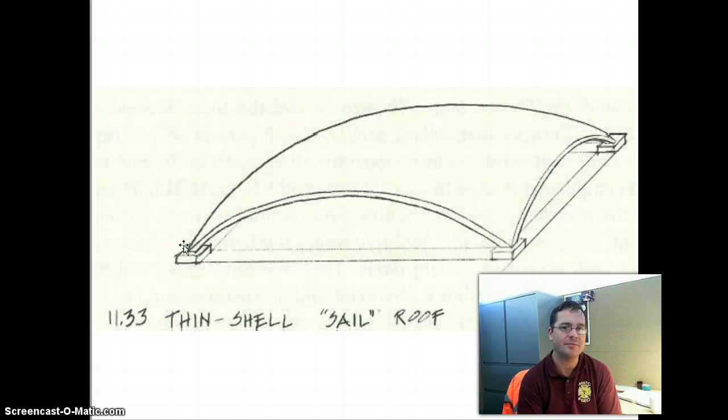You have to have something to keep the soil from sloughing into the excavated hole, because typically the walls of the excavation need to be near vertical. They don't have the luxury of cutting the walls of the excavation back beyond the friction angle of the soil. So there'd be a number of ways you could retain that. You could drive sheet piling, for instance. You could drive piles and drop in breastboards and rakers. That's all expensive. So an alternative method is you spray shotcrete on it.